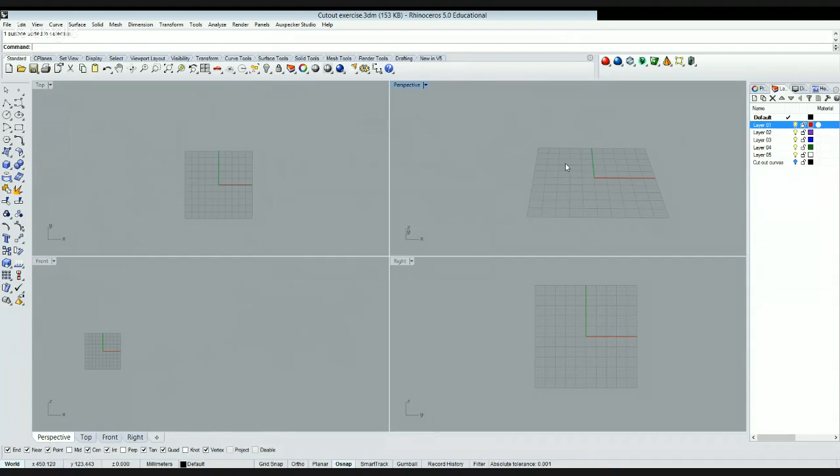This is my surface, and from this I'm going to create all the shape that you saw in the beginning. Let's organize a little bit our layers. I will create a layer for the auxiliary lines. Okay, and by selecting this line and right clicking on my layer, Change Object Layer. So now whatever I don't need, I will put in this layer. And I'm going to turn off the preview of it so we are not getting confused.